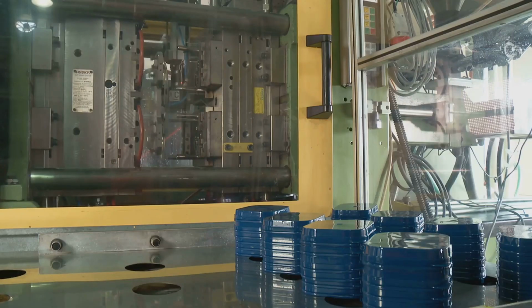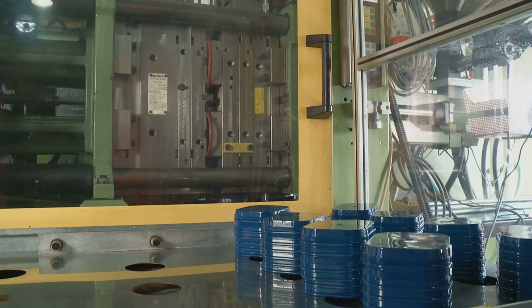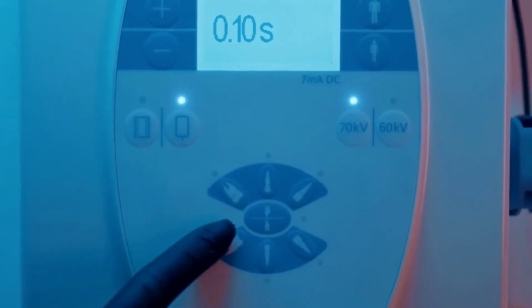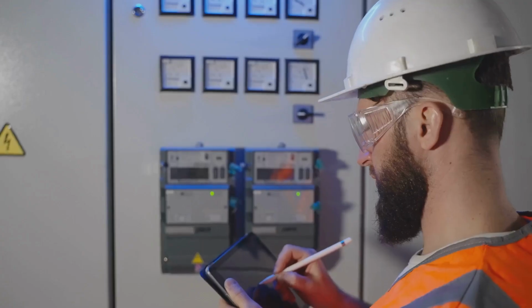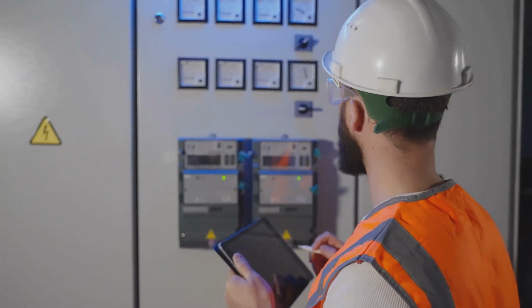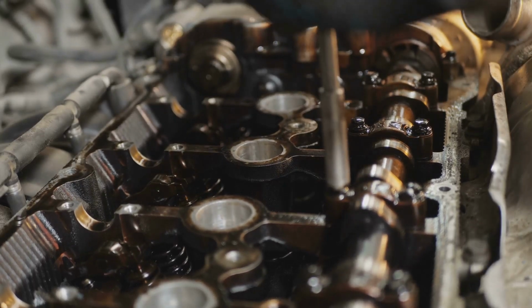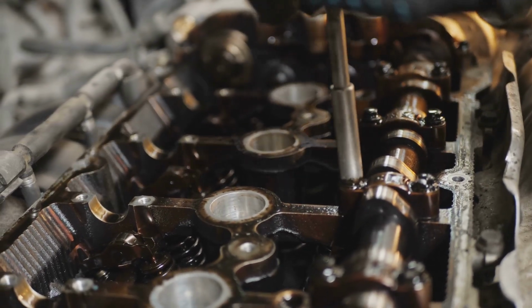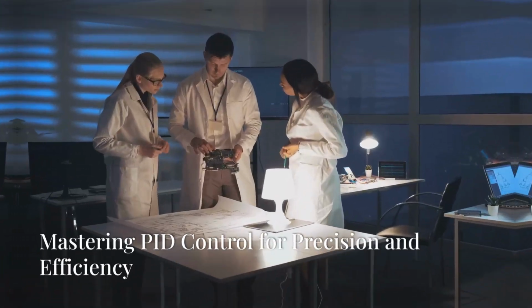For systems that experience frequent changes, consider implementing adaptive tuning techniques. These techniques automatically adjust the PID parameters based on the system's behavior. Periodically, review the PID controller's performance and make necessary adjustments. By adopting a proactive approach to maintenance, we can ensure our PID controllers continue to operate at peak performance.